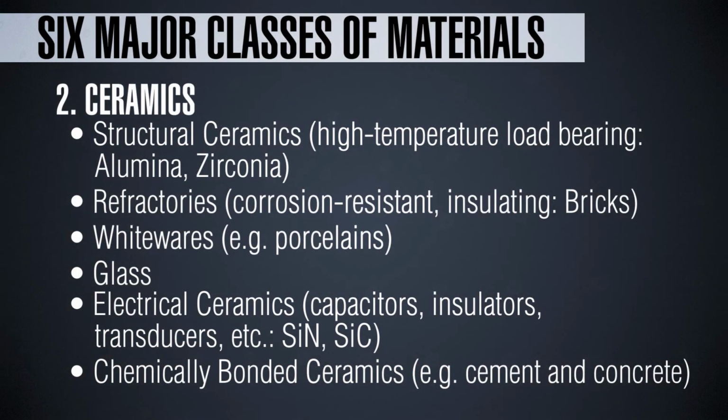Silicon carbide is also a very important material for electronic applications because, well, it has an indirect band gap, but it has a huge resistance to high temperatures, meaning that you can realize electronic circuits using silicon carbide instead of silicon for applications requiring resistance to higher temperatures, or where the current density through the device is so high that thermal heating by means of the Joule effect could destroy a standard device realized in silicon.